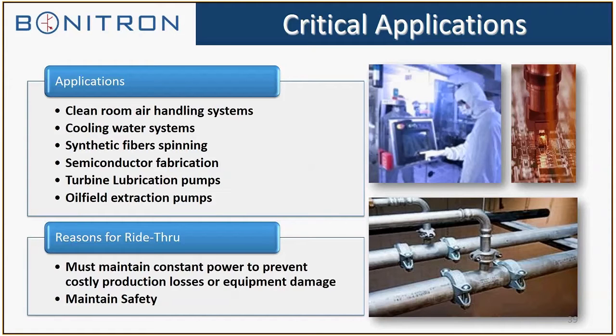Now, where and why do we use ride-through? What do we look for in ride-through applications? I put up some of the applications we've done, but this isn't limited to just these. Anything where the process, or whatever product the customer is providing, or trying to back up for, say, an environmental system. And we look for the critical processes which can have no speed or torque change of the motor. So in other words, it has to be a continuous process. There can't be any interruption or deviation of the drives running the process.